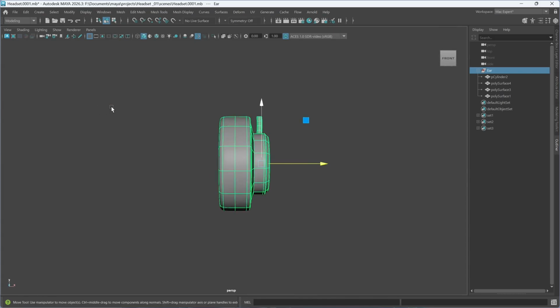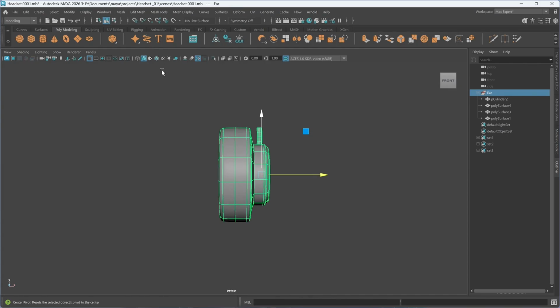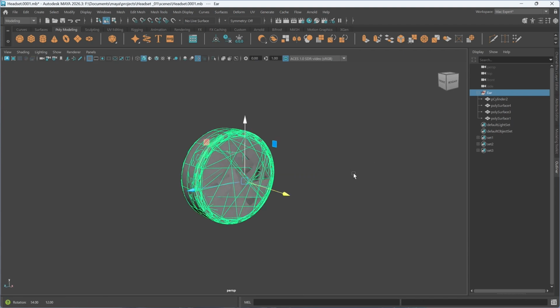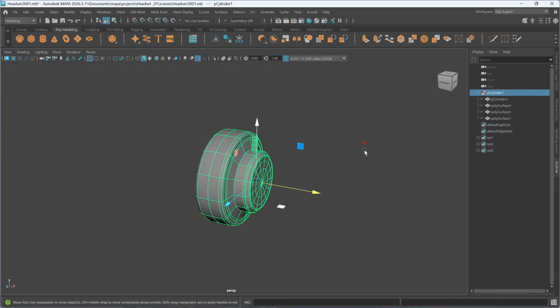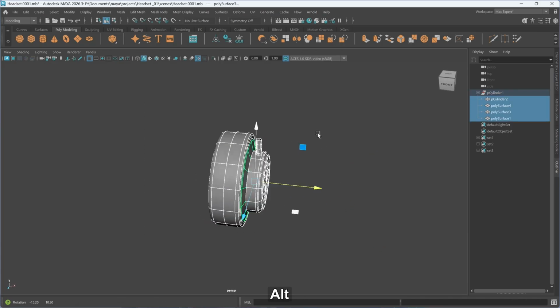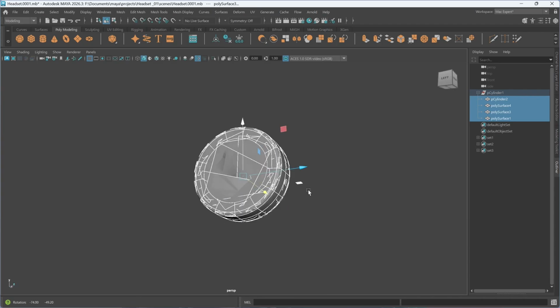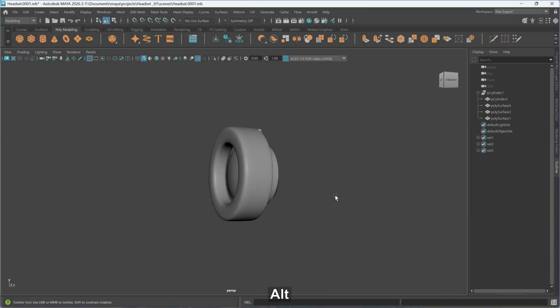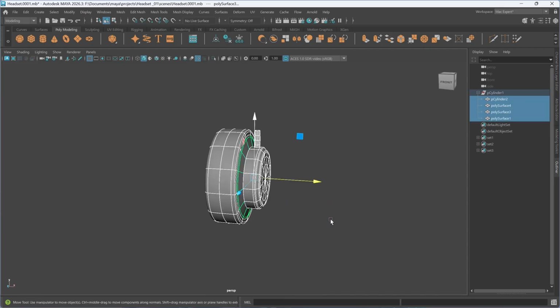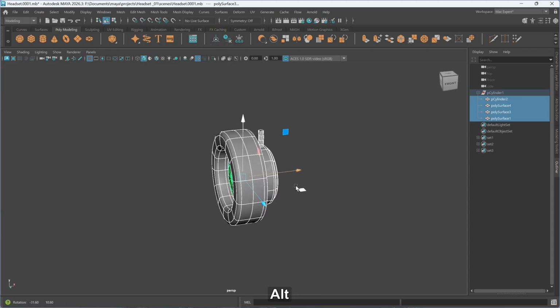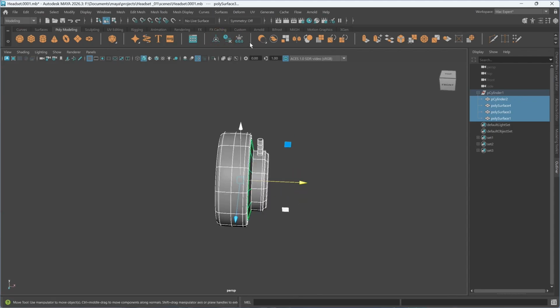So now another way you can do this is by going over to the poly modeling shelf, center the pivot, that is doing what we don't want. So I'm going to select everything. This is center pivot. Okay, now we're having so much issue. I've never experienced this before, but let's work on that. So I'm going to select everything. Let's delete history, freeze transformation, and let's center the pivot. Now you can see everything works because we have not frozen the transformation while everything is in the group.